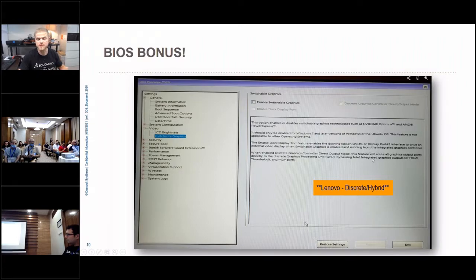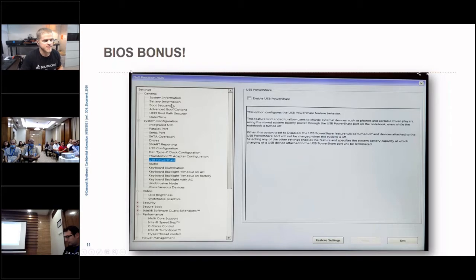If you turn this off, you can force the machine to always use that higher end card, the bigger graphics card. And again, the intent here is to save energy. So if at all possible, the machine would try and use the smaller one, but use the bigger one when needed. I saw a lot of problems with that, though. I saw a lot of problems with it trying to switch from one card to the other. So again, this is a test. If you're seeing a graphics issue, if SolidWorks is slow, turn this off, see if it helps you.